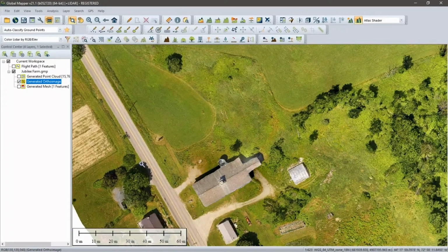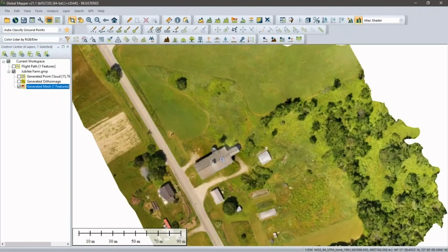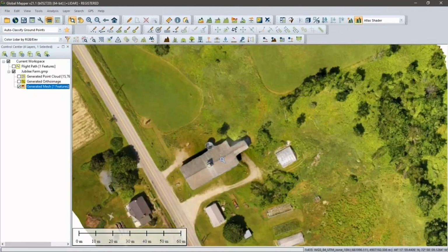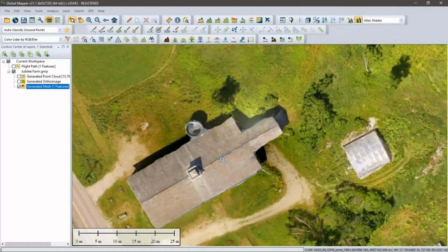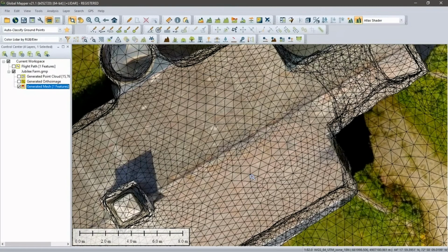You can see the lines in the road. You can see our simulated ground control point here. Again, so you can see what it is in the actual image itself. So that is our ortho image, and the final output is going to look similar again. It is our mesh. In the 2D view, top-down view, it looks similar. If I zoom in a little closer here, we'll actually see the components of the mesh. The mesh is actually a vector file, and you're seeing the interlocking triangles here that derive the model. This is what it looks like structurally.